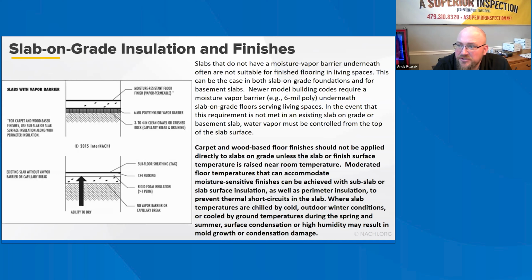Once any pre-existing moisture issues with the slab are addressed, a floor finish assembly that can accommodate a small amount of upward moisture flow can be installed. One viable approach involves the use of rigid, semi-permeable insulated sheathing greater than 1 perm, such as extruded polystyrene on top of the slab, with 12 to 16 inch on center furring above the foam, followed by a layer of tongue and groove plywood for the subfloor. The finished flooring above the plywood should be a breathable finish, so impermeable materials such as vinyl flooring should be avoided. With this type of assembly installed, a relatively dry slab with a sub-slab layer of poly can be finished and designed to accommodate a limited amount of moisture that dries upwards.